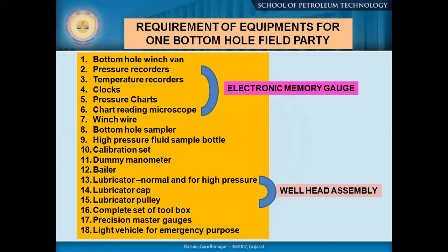So as an engineer, you should be very careful to keep some things in mind. One, before doing your bottom hole operation, you must run your dummy sampler or dummy gauge, so that you know your well is clear up to the desired depth of study. Number two, your operation should be accompanied by a light vehicle for emergency purposes. This is the most important part.